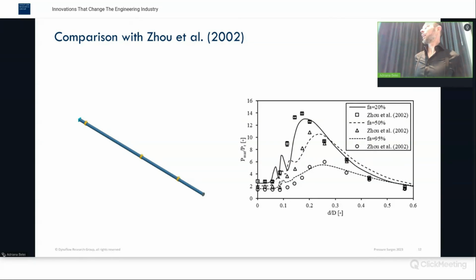And so, why is that? Because when the liquid gas interface travels through your system, you can assume, of course, that little bubbles will be present at least in the first part of the liquid column as it travels through the system, and especially when you have lots of bends, etc. There will be some mixing there, and those bubbles have a higher compressibility, so they effectively lower the wave speed of your liquid. And in order to match these results, we also had to lower the wave speed in order to take that into account. So this, I think, is the largest drawback of our model, that we don't do this at the moment.